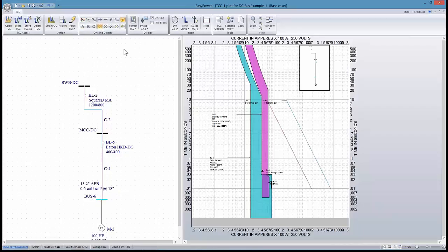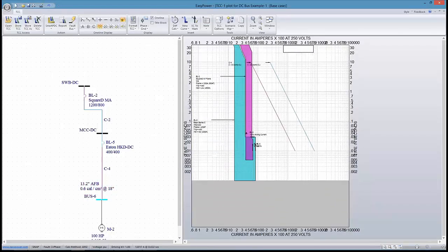over here. If I show my incident energy, I go back and put the breaker where it was, we have a high level of incident energy with this arcing current. If I reduce the setting on the breaker just a little bit so that the arcing current now falls into the instantaneous area of the trip settings, I get a reasonable incident energy even with the settings I had before. All right, let's go back and do the same thing now with the bus above this.